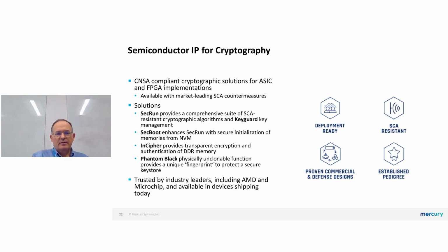Encipher is an important anti-tamper solution that provides transparent encryption and authentication of DDR memory as protection of DDR memory at runtime. This can be realized in devices like Xilinx's MPSoC, where you can, in the hard processor subsystem, run an operating environment like Xilinx's Linux or another operating environment from a third party.